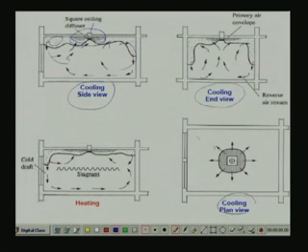In this particular view you have only one ceiling diffuser and the air is distributed in all directions. However, if you are using this for heating applications, there is a possibility of developing a stagnant zone. Again because of the buoyancy effect, the warm air tends to rise up rather than come down. So, near the floor you may have a stagnant zone.